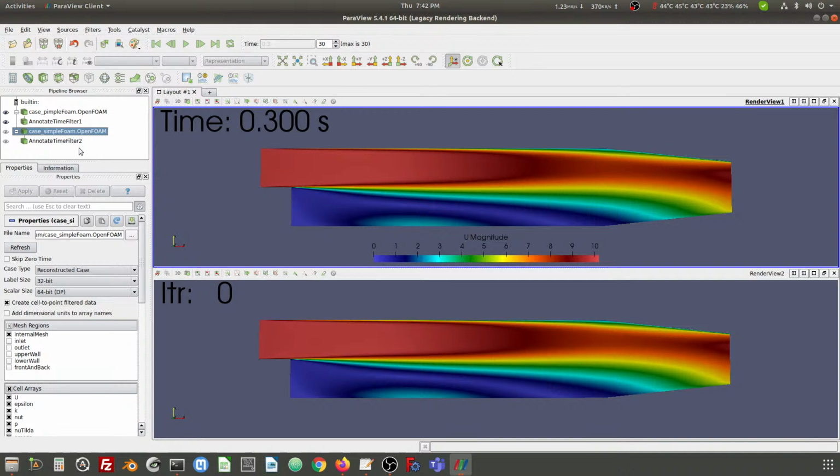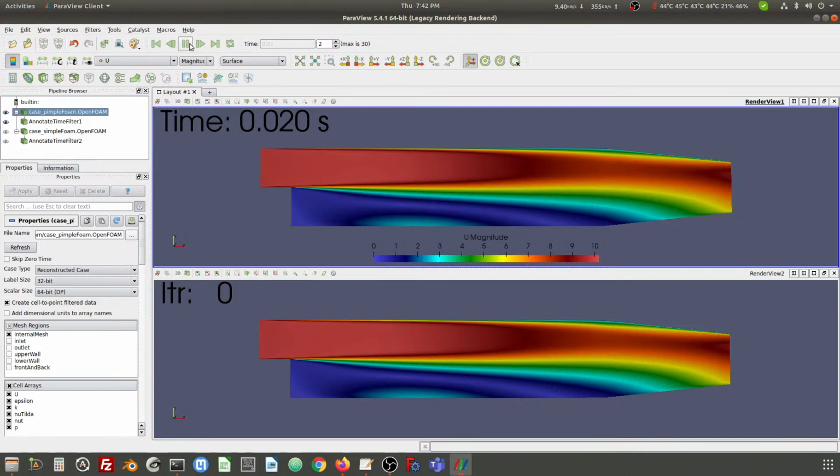Basically if we run the simulation for more time, then we can see the difference, some change at this time. So let me just play continuously. You can see the static simulation, nothing changed, but here you can see some changes, the velocity changing. Initially we took this flow field variable values, then we mapped them to our tangent simulation, and then we ran the whole tangent solver pimpleFoam.